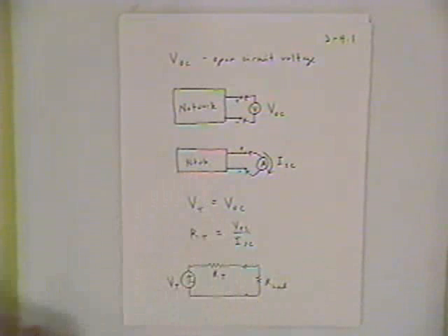The advantage of the Thevenin equivalent is that this equivalent network could have, as I showed before, multiple components, lots of sources, lots of resistors, other elements. And all you really have to do is make two measurements at the open circuit, the voltage, and then short that out with an ammeter to measure the short circuit current. So thinking in terms of a laboratory measurement, it gives you a very useful way of figuring out what's inside a gray box that you don't know the details, and you just have those two wires accessible to you.